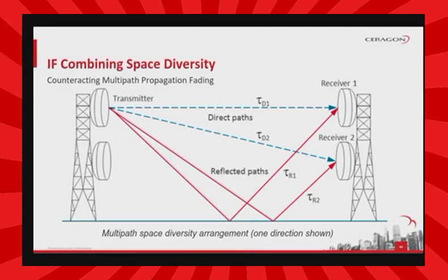As the multipath transmission is typically caused by fluctuating layers in the atmosphere or at ground level, the delay difference between the direct path and the reflected or deflected paths vary over time. Also, the reflection coefficient, that is the strength of the reflection or deflection, varies over time, resulting in erratic fading behavior. By putting a second receive antenna on the tower, with a vertical separation from the first antenna, we create a second set of delay combinations.